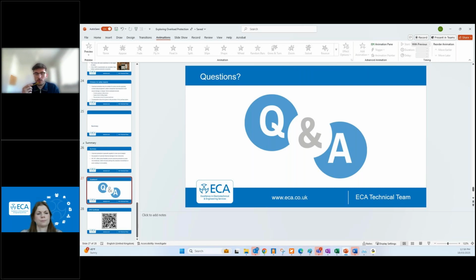So it may be that you can design out the requirements for an RCD. You may be able to protect it by a circuit breaker, for example, and then you would just need to confirm that the circuit breaker was suitable for bidirectional energy flow, which I believe most of them are. So hopefully that answers the question. And the same would apply for any circuit where there is the possibility. I know batteries was mentioned. The same would apply for that.